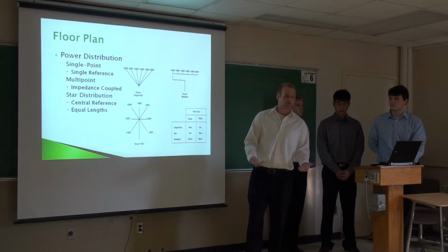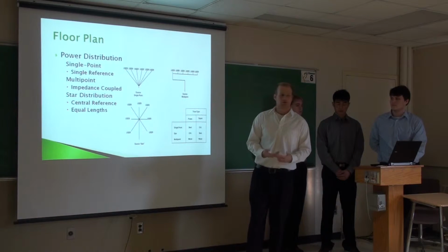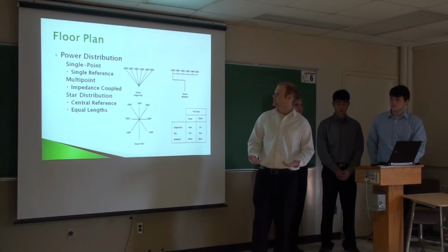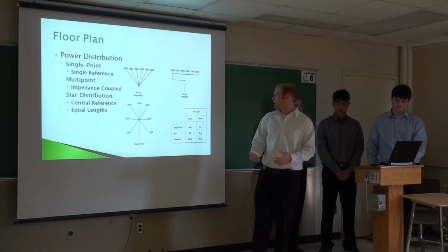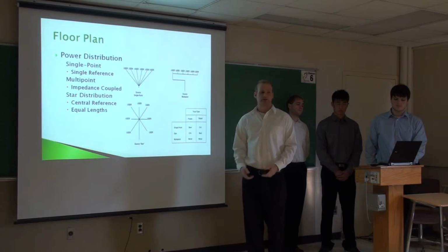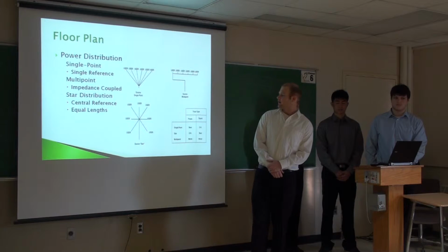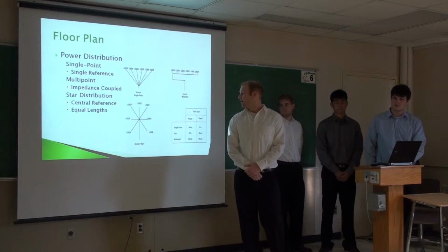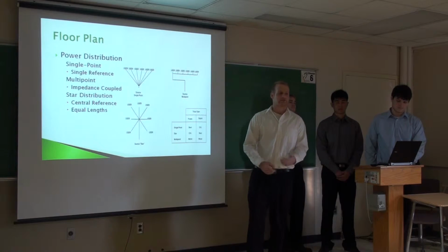So when you're designing, which is the best one to use depends on what you're going for. If you want the best power, you generally want to use single points, so all the current's going to be flowing in one direction. And if you want the best signal processing, you generally want to go with star distribution, because say if there's a delay in the system, since all the user components are equidistant from the reference voltage, all the delays will be experienced at the same time.